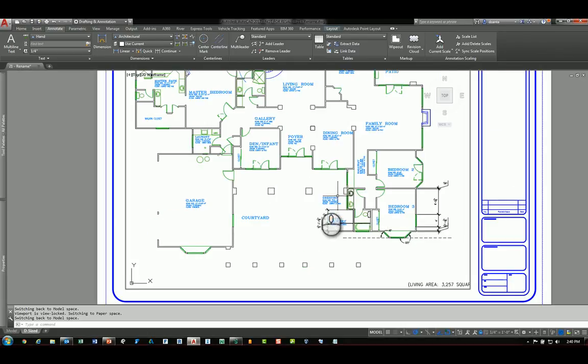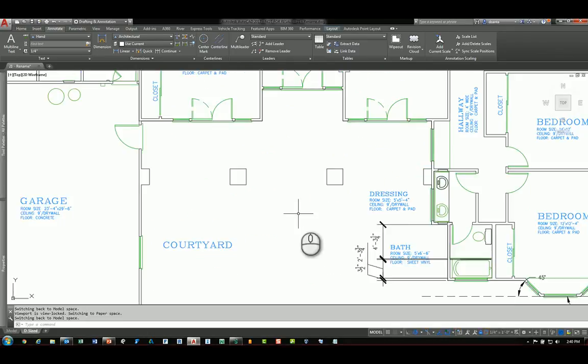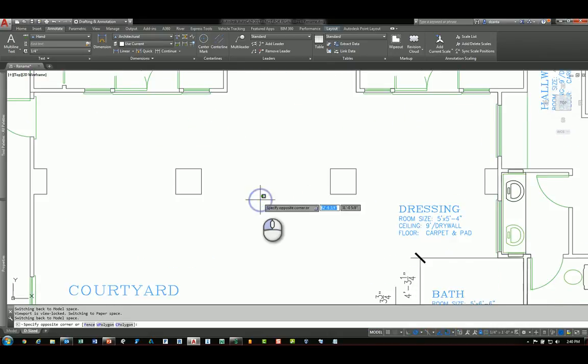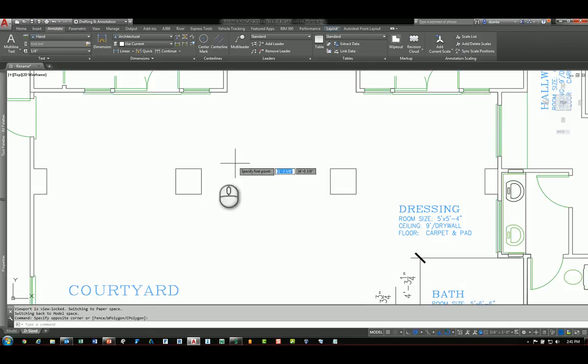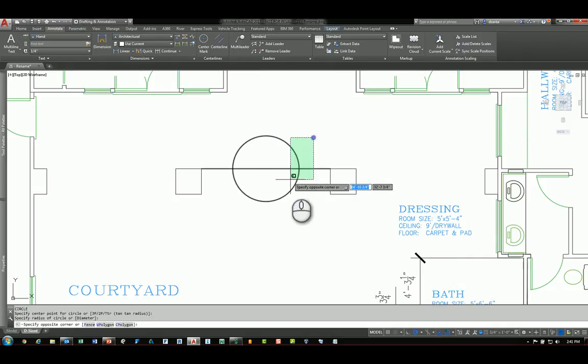Another tooltip is the ability for you to draw an object where it is dead center between two other points of reference. An example would be as follows. I want to draw a circle such that the center point of the circle is right here. It is between this corner and this corner from a straight line, or even if this object and this object is not even perfectly aligned. How do we do this normally? We would draw a line from this end to this end, and then we would draw a circle from the midpoint out, and you'd get that result.